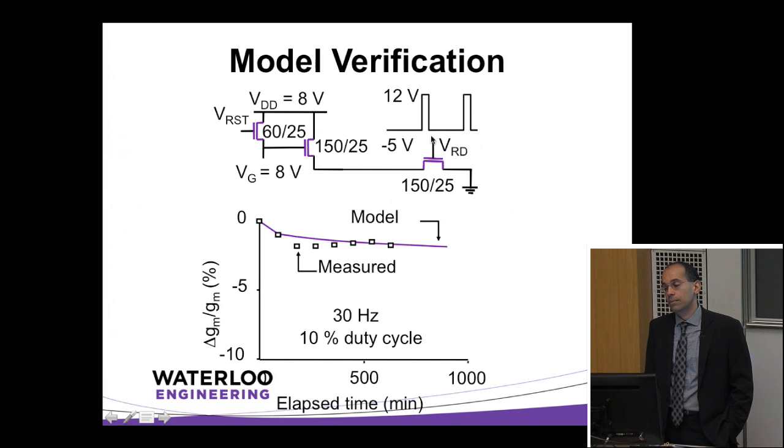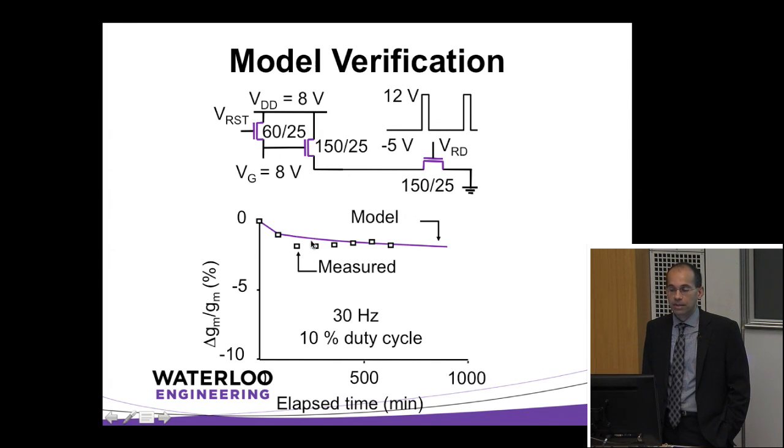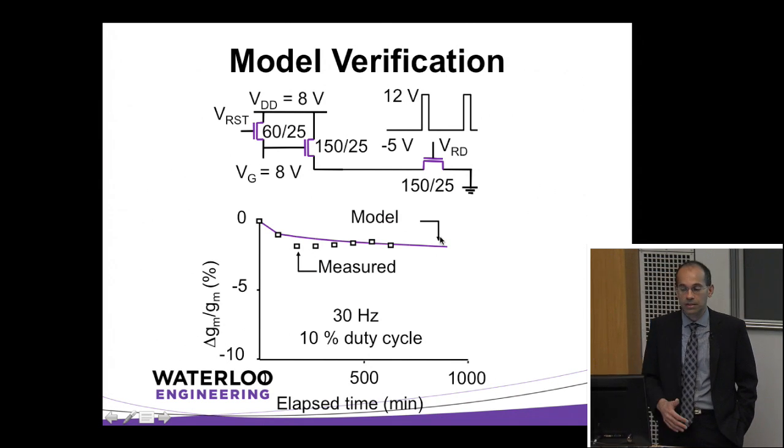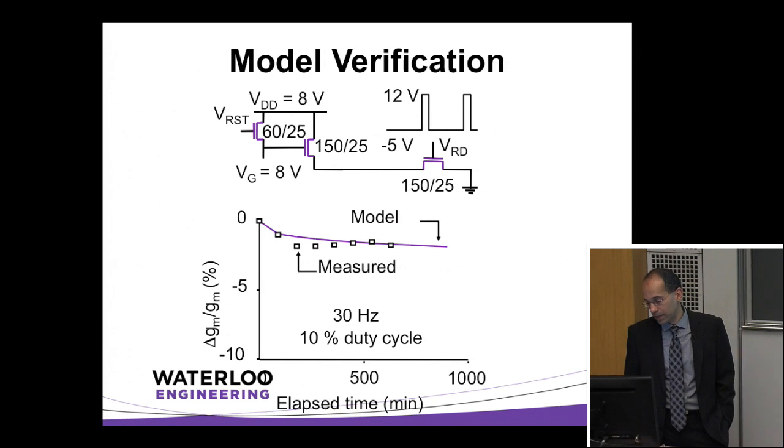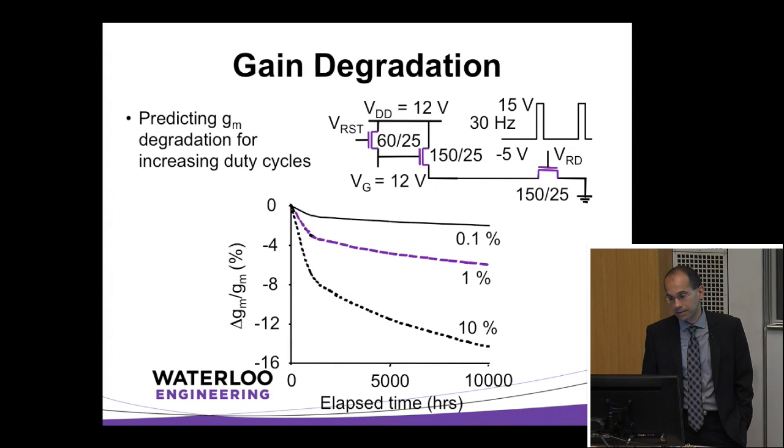So when we actually did the modeling and measurements on our active pixels, what we found is that, yeah, you get some degradation, but actually there's some kind of a compensation that kicks in. So the degradation is not continuous. It's not going down all the time. It actually saturates after about, say, 1,000 minutes or something, right? So this was quite a relief as far as we went.